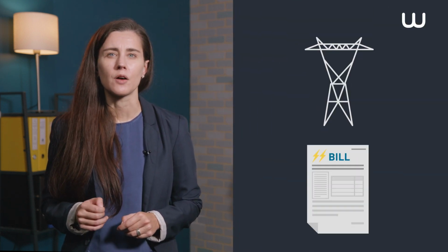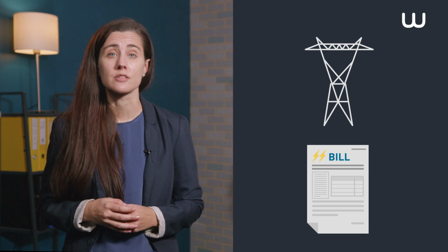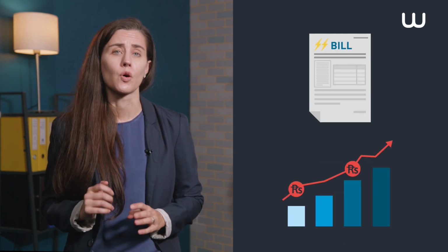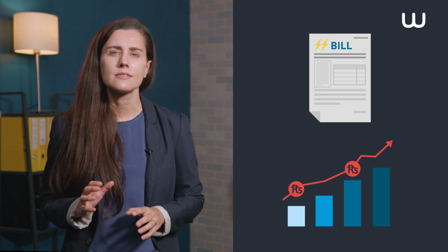Customers connected under medium and high voltages are generally concerned by the billing of reactive energy by electricity suppliers. This can significantly increase a bill for a water utility. It is therefore important for major consumers to implement suitable offsetting measures for reactive energy, in order to both reduce their electricity bill and stabilize the quality of the current supplying power to the equipment.